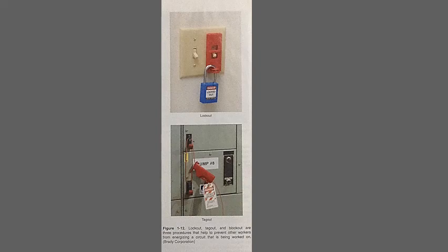Turn the power off. These four words will be repeated to you throughout this book and probably during your apprenticeship. Turn the power off. Never work on energized equipment unless it is absolutely necessary and you have the proper training, equipment, and PPE. Turning the power off will take more time than the actual work. It is not a reason to work on energized equipment.